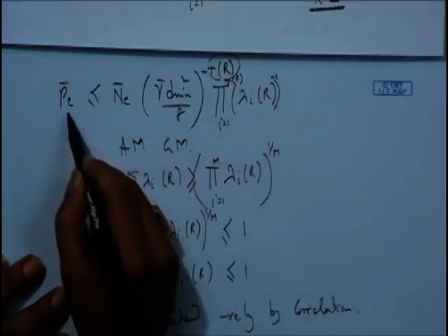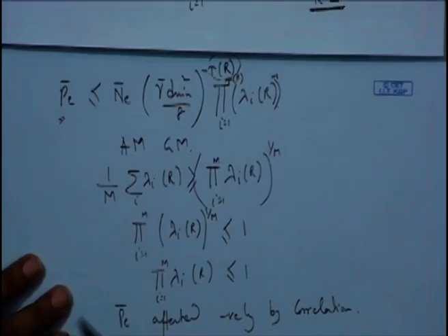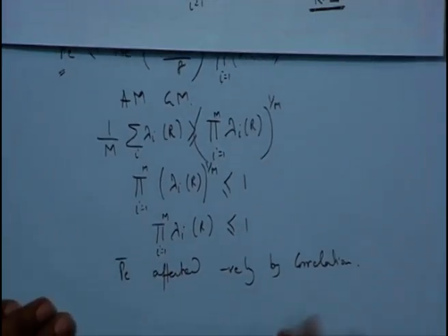So overall Pe bar increases when compared to a spatially white channel. So in summary, if there is correlation present, the probability of error is affected in a negative way. Moving on forward, what we'd like to add is suppose we have a Rician effect, a Rician channel.